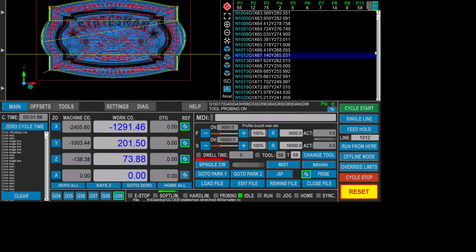In normal use, if you're using the same tools every day, in the morning you just switch it off. It's on for safety, just to make sure that the tool does get probed, so you haven't got any mismatch of tool lengths. So to switch it off, just press this button until it says tool probing off in the display here.